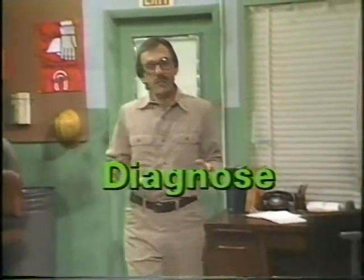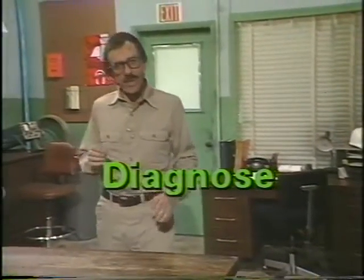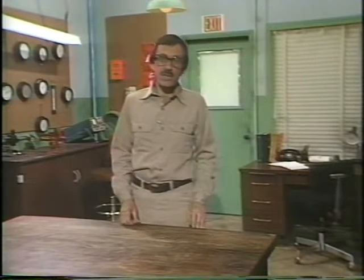After you've finished observing the system, you'll need to diagnose the problem. In other words, you try to identify what instrument, piece of equipment, or section in the system would most likely be causing the problem. Pin it down to a specific part of the system if you can. Diagnosing the problem is the first place in the troubleshooting procedure where you're going to have to make a logical conclusion about what the most probable cause of the problem is. The more you rely on a logical procedure to guide your thinking, the better the odds are that you'll diagnose the problem correctly. And to a large extent, your skills as a troubleshooter are going to depend on how well you're able to diagnose the problem.